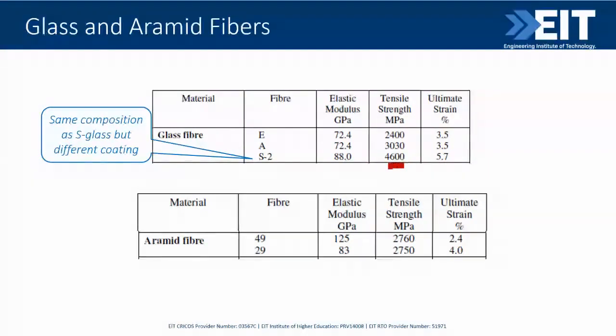So we see this can come to again quite 4 gigapascal, 3 gigapascal. We've got 2 grades. One is called E-glass, for general purpose structural applications. Another one is S-glass, which has higher strength and heat resistance as well, and the higher spec of X2.